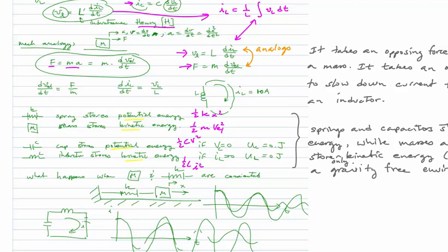Electrically, the exact same thing happens. You put a capacitor and an inductor together in a circuit like this, and if there is no resistance, no loss in that circuit, which physically you can't have, but you can come close, and you give some initial condition, either potential energy as a voltage across the capacitor, or kinetic energy as current flowing through the inductor, you let this thing go, it will oscillate. And of course, it'll decay if there's loss in there.